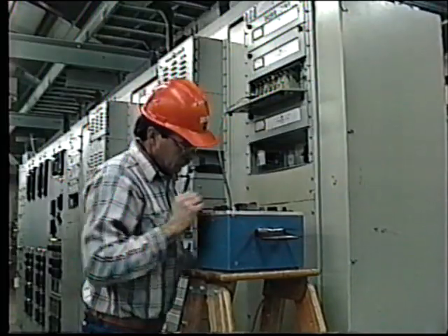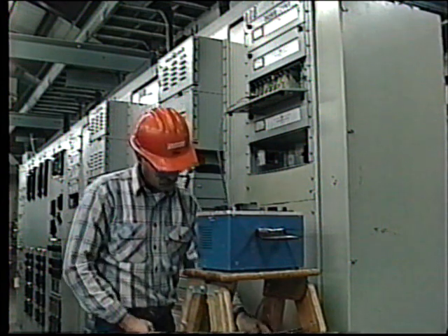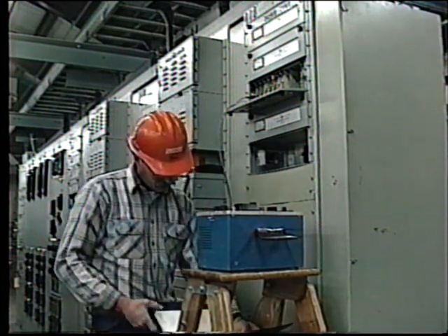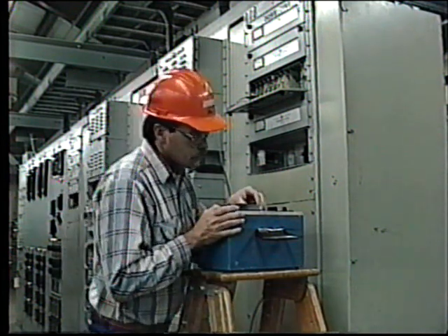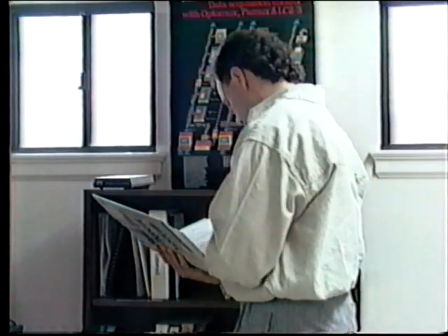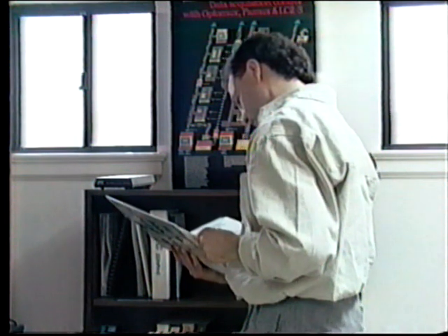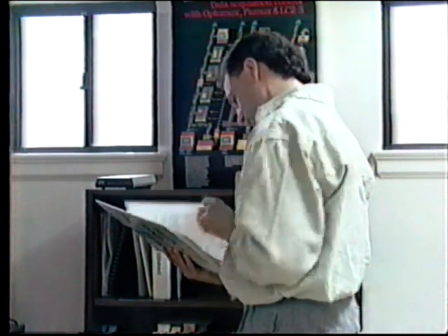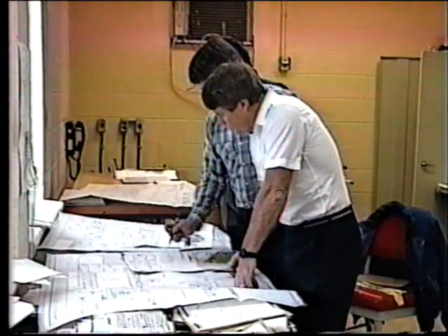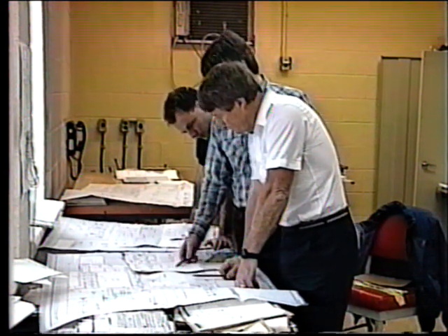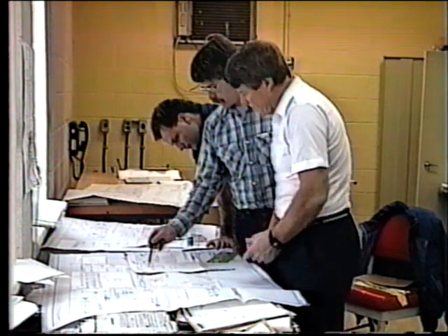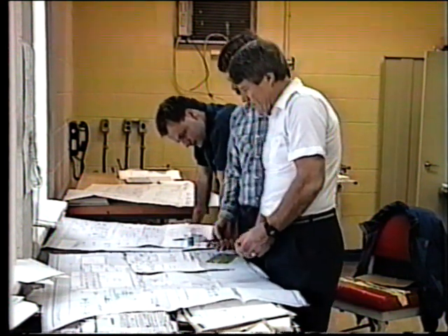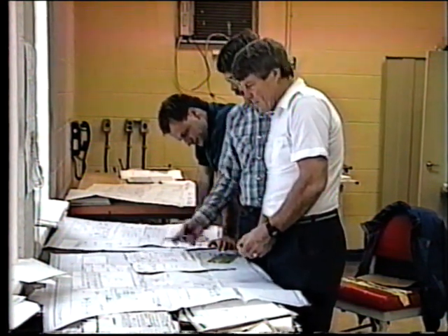It is essential that good maintenance records are kept. All test results, calibrations, and preventive maintenance actions should be logged and filed for easy access. In addition to this, installation and commissioning test reports should also be available to the maintenance technicians. It is extremely important that complete maintenance instructions are available, including drawings, schematics, and step-by-step descriptions of tests and adjustments which are required.